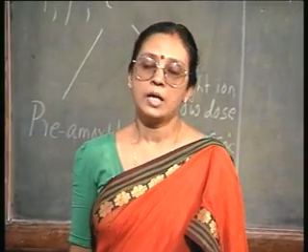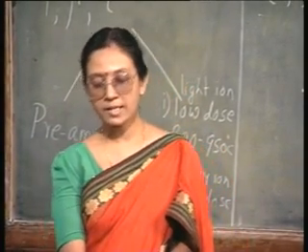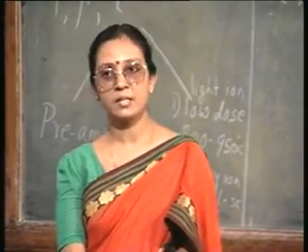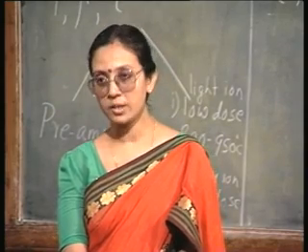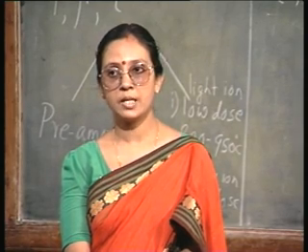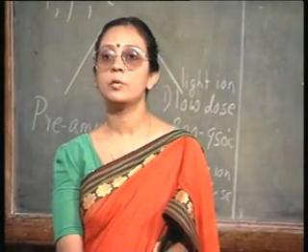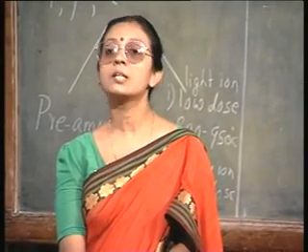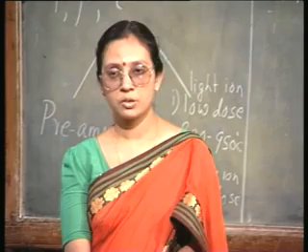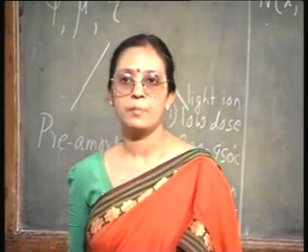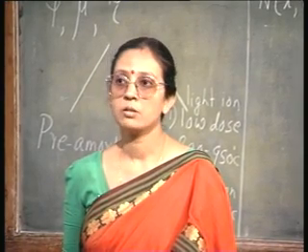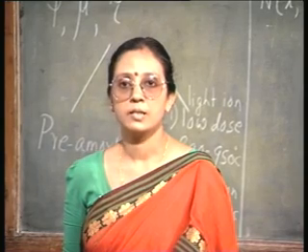Okay. And on the other hand, in case of laser annealing, you have a pulsed laser beam which can melt the amorphous layer and then recrystallizes without any extended defects. Okay. So you see, again the recovery will be total and it will be very fast, because you are actually doing a recrystallization. You are very quickly removing all the damage. So these are the two major branches of rapid annealing, which are very popular nowadays after implantation.